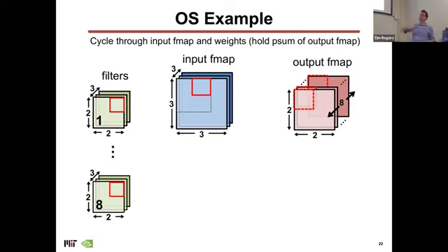So those local registers inside the processing elements are accumulating the result that performs these dot products, these convolution operations that are happening. And we do the same thing with the rest of this particular slice. Then we've got a partial product for what we want on that upper right-hand side. Then we have to move now to the next channel, right? Because that was just one channel.